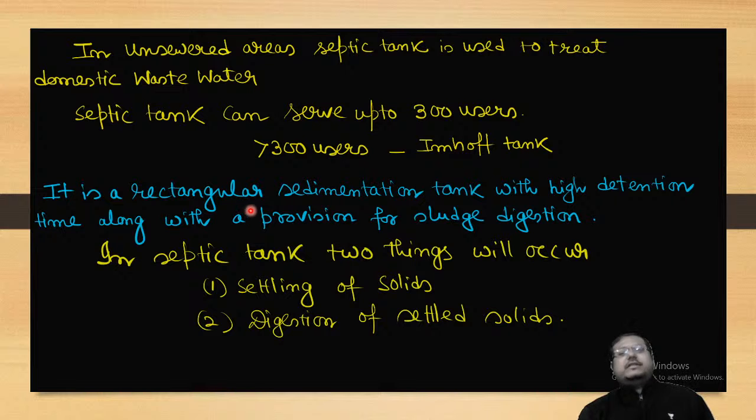It is a rectangular sedimentation tank with high retention time along with the provision for sludge digestion. In septic tank, two things will occur: settling of solids and digestion of solids. Settling of solids does not require any kind of microbial assistance, so it doesn't matter whether it is aerobic, anaerobic or facultative.